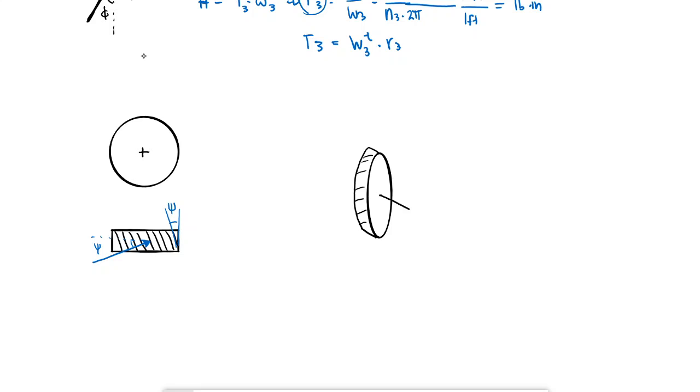I'm going to have X, Z, Y. I'm going to have a force that is in the same plane as XY, okay, which is causing the tangential, the rotation. Okay, so if I was to draw the tangential one, just like I did for the spur gear, this would be WT, tangential one, times the radius R, whatever the radius of the gear is, that would give me the torque. That's why this is what I can calculate, WT. Okay, that would be located here.